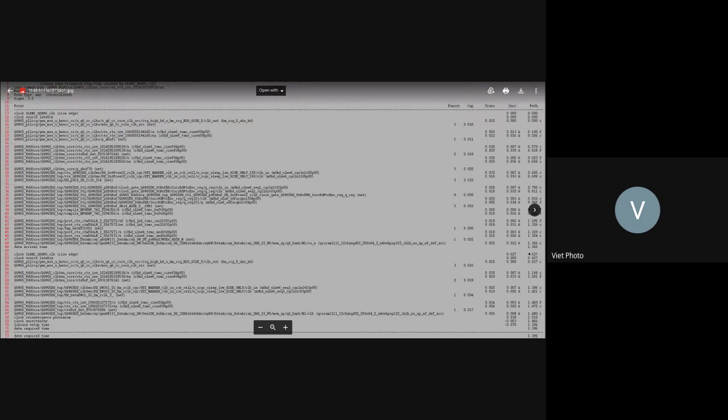Remember, the first edge is launching, so the next flop will be calculated at the next edge, not the same edge, because the same edge means you have 0 picosecond, right? So you have to check at the next edge. The next edge means you have to add the period. That's 627 picosecond, that's the period.